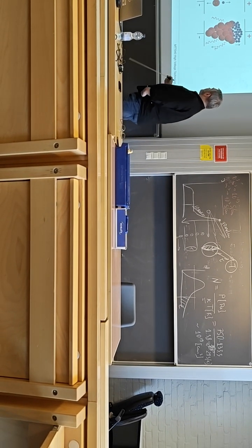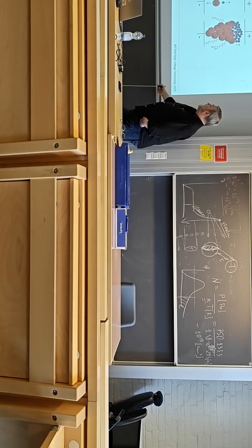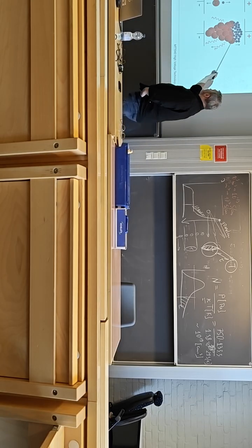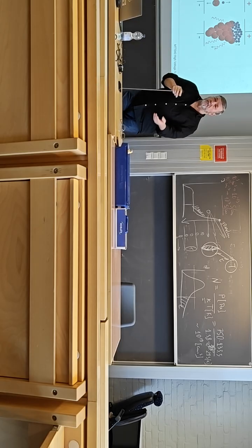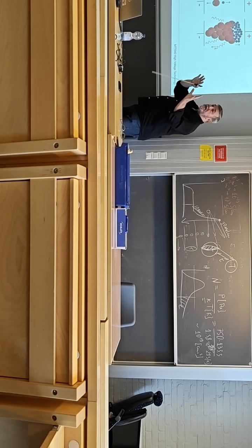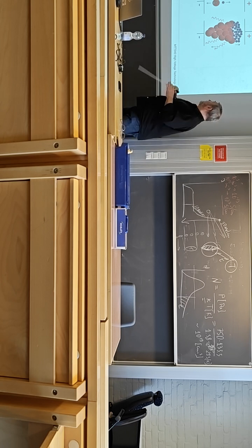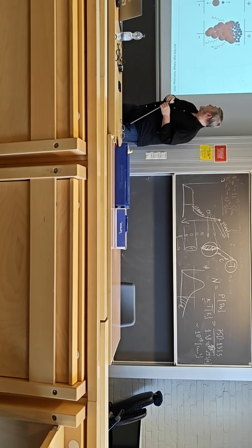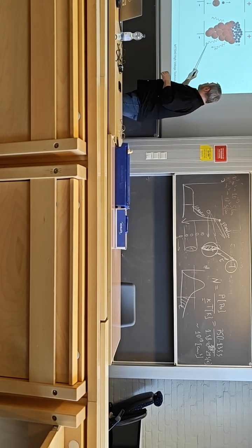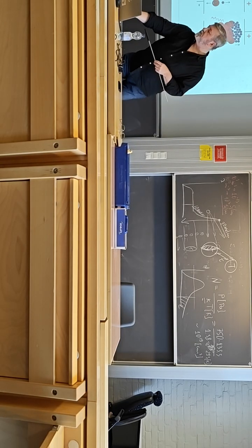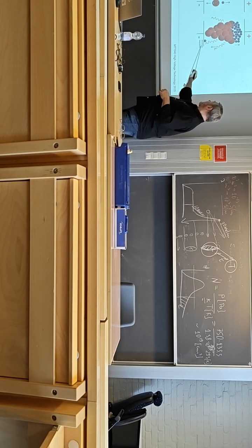There could also be some recombination between these two, which may lead to the release of photons. These photons are why you see, normally in air, some UV blue light from the discharge. These are the photons generated due to recombination, and when they reach the cathode and have enough energy, they can release secondary electrons, right? That's what may happen here.